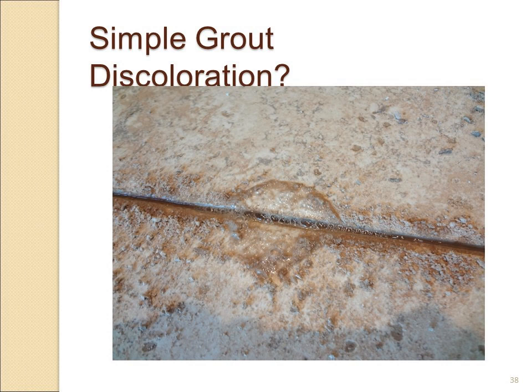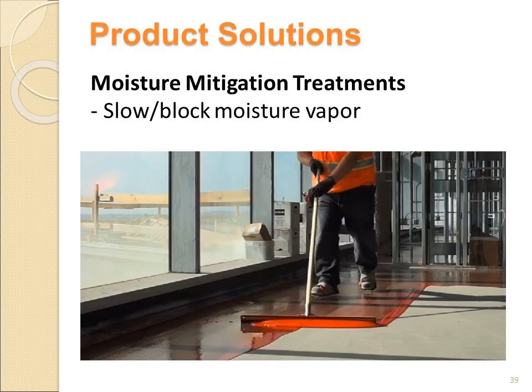So we have to ask ourselves, well, what steps can we take? What products can we use? How can we address moisture ahead of time so we don't run into these situations? Well, there are some rock-solid areas that we can address, things that are definitely proven to handle moisture up to 99% relative humidity, up to 25 pounds of moisture vapor as measured by calcium chloride, and those are products that meet the ASTM for a two-component epoxy moisture mitigation membrane.